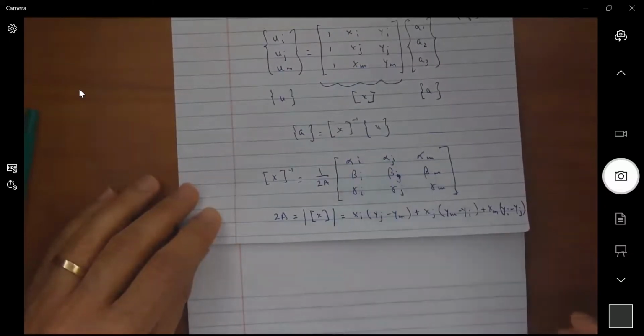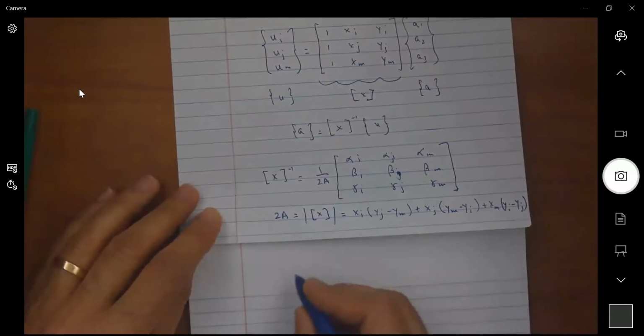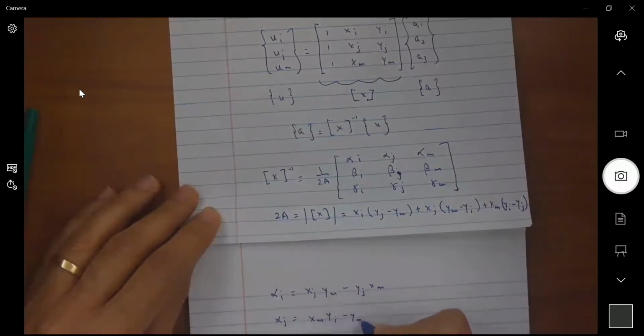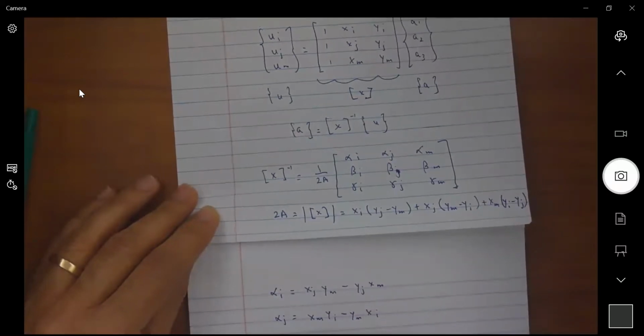If we evaluate the cofactor matrix elements, I will get an alpha I that is equal to Xj Ym minus Yj Xm, and alpha J that is equal to Xm Yi minus Ym Xi, and alpha M that is equal to Xi Yj minus Yi Xj,